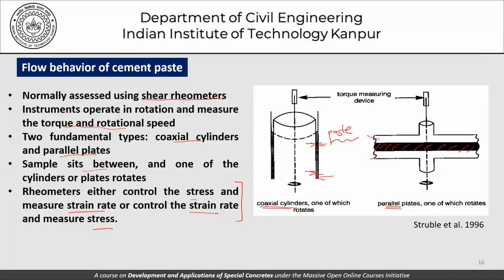In this context, please remember that these instruments and this whole thought process and theory was not developed with cement paste in mind. It was developed for other fluids or suspensions with very fine particles. What we want to do is to study the rheology for cement paste, where we still have fine particles in the water, that is fine. But when it comes to mortar, we have particles up to about 4.75 mm. That's what sand is, and sand is a part of the mortar. When it comes to concrete, then we are talking of particles could be even 20 to 25 mm.